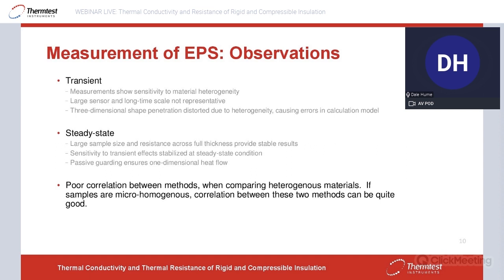There has to be, because it is not homogeneous. What is the degree of that distortion and its effect on the calculated conductivity is specific to the material testing. The greater the difference between the particle or phenomenon that's causing the degree of heterogeneity and the matrix, the greater the distortion of that shape. Again, it expects that heat is penetrating in all directions the same, so three-dimensional. So when it's not three-dimensional, there's an error in there. The amount of error is really specific to that material.